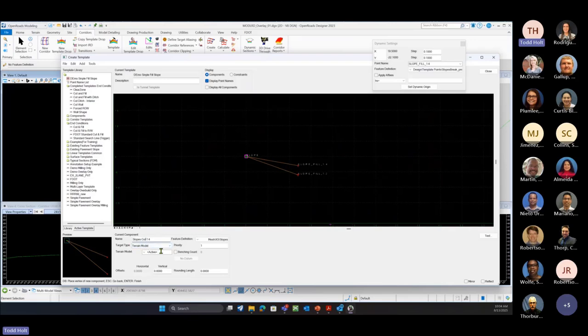And we're going to go 1 to 4. It's going to be a terrain. We'll leave this. So we'll go back and set everything. Anything new, we're going to set that to 1. We already have the 1 here, so on our cut slopes, we're going to set that to 2. I'm thinking I may have to change that. So we're going to do our slopes. This will be our point name. We're going to set that to cut.